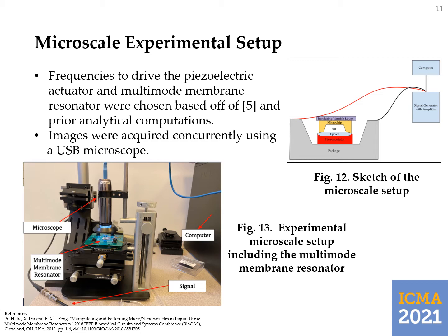One thing to note, we also applied an insulating varnish layer on top of the entire chip because we would be moving to water and I didn't want to short anything and also destroy the chip. And also there is an air bubble in between the microchip and the piezoelectric actuator, similar to the reason why a drum head needs some air in between the top membrane and the table or whatever the drum head is on. You need a space to resonate.